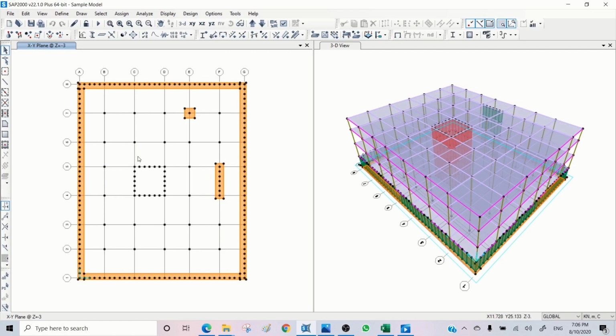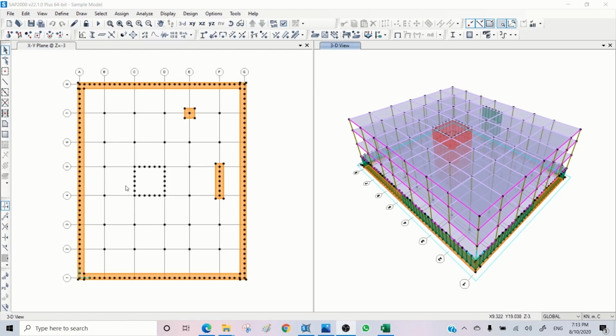If they are top builders, they don't mind. If they are normal builders, they maybe actually have a bit difficulty in supplying. So you need to see whom you are dealing with and what is the scale of the job to make the right decision about the thickness and grade of lift pit wall. So let's draw the lift pit wall. Just to save the time and ease of modeling, I'm using the same wall property as lift core wall.